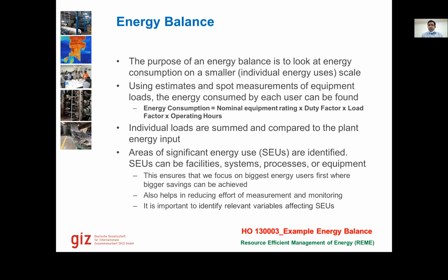Another way is to put up a power data logger there, which logs data for 1 day or 2 days, and then we might have more data. So there are different means of measuring this. And then we sum up all the individual loads, and then we can compare it with the plant energy inputs. Then we need to identify significant energy uses.